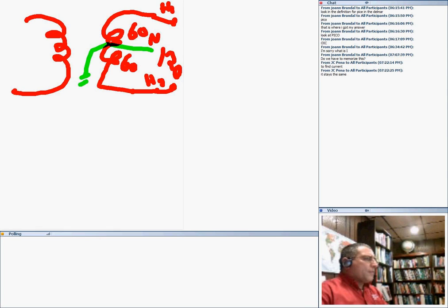The advantage of series circuits in the power industry is how you can connect the coils. Everybody see that? You connect the coils in series to get your voltage. On the generators it's the same thing, guys, exactly like the transformers, and on the motors too. But we mainly do it on the transformers, so you can get multiple voltages out of the same device. Any questions, guys, about this?